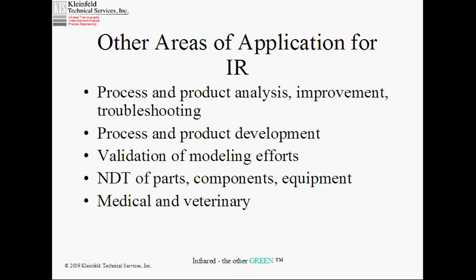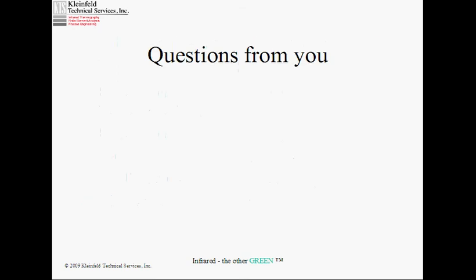Yes? To any extent, can you see reinforcement? If they're large and shallow. If they're deep, kind of not. Because the concrete is actually fairly diffusive thermally, fairly conductive, so that the signature spreads out fairly rapidly. If you didn't want them near the surface, correct. All right, so non-destructive testing of parts, components, equipment, and there are medical and veterinary applications as well.